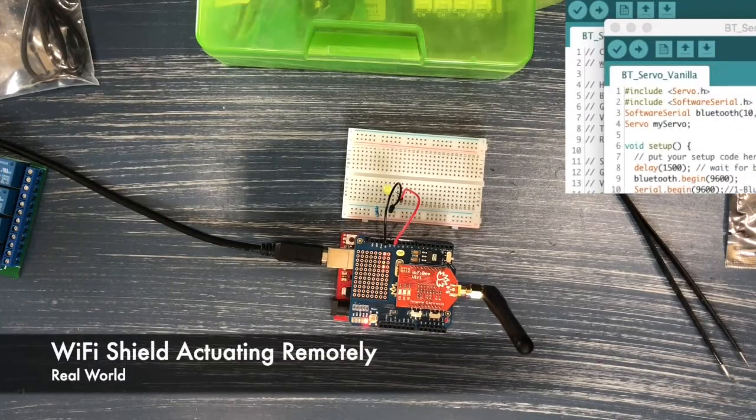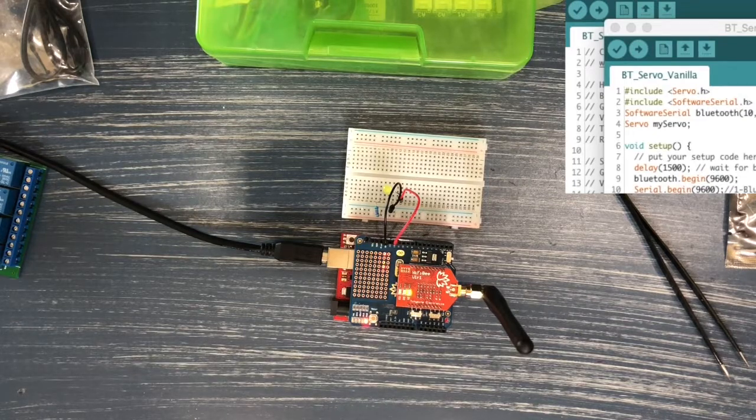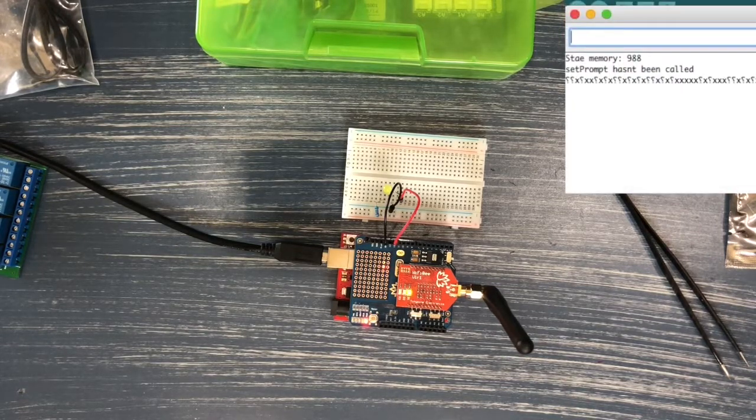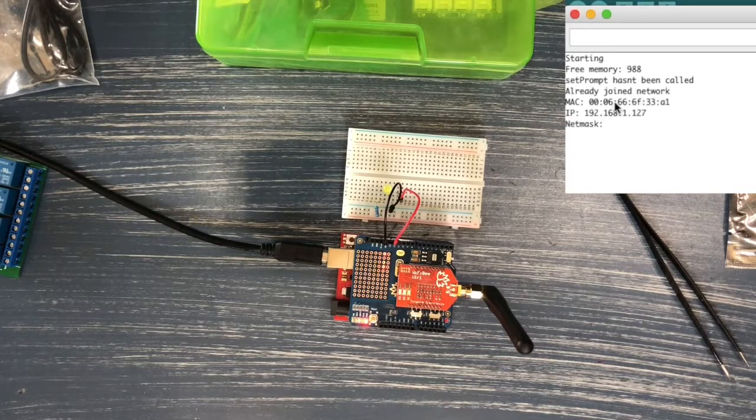We're going to open the serial monitor, in this case, simply to look at debug code. Most of the time that we print stuff out to the serial monitor is mostly for debugging purposes. So in this case, we have the Wi-Fi shield. Oops, it's at the wrong baud rate. There we go. So we can see some debugging messages in our serial monitor, and it is what we expect.